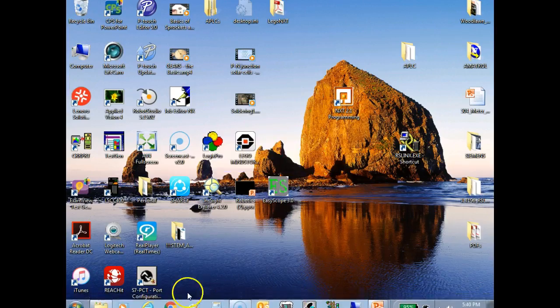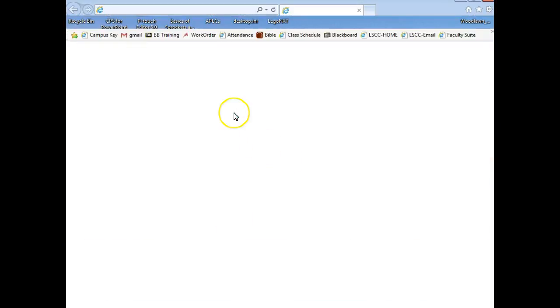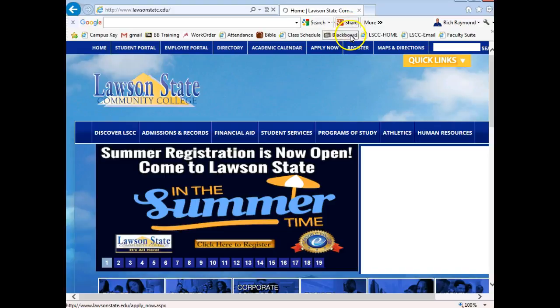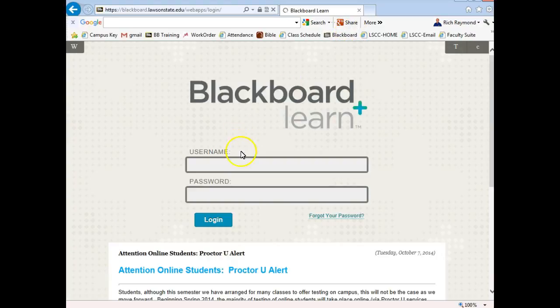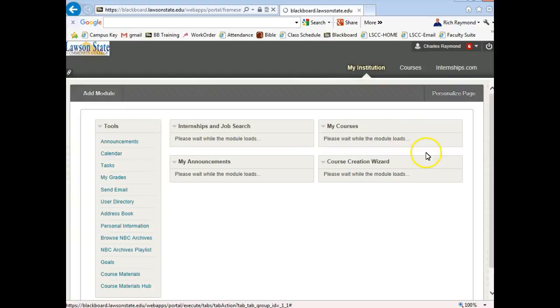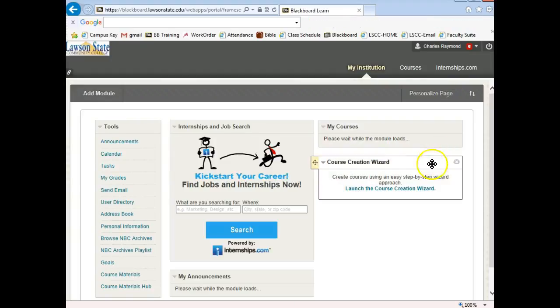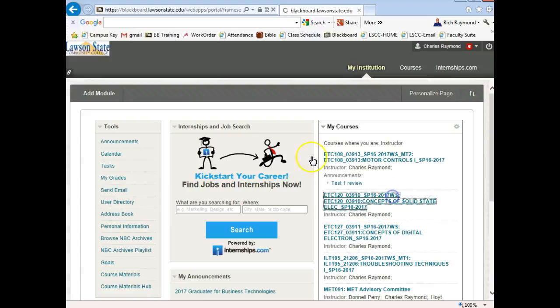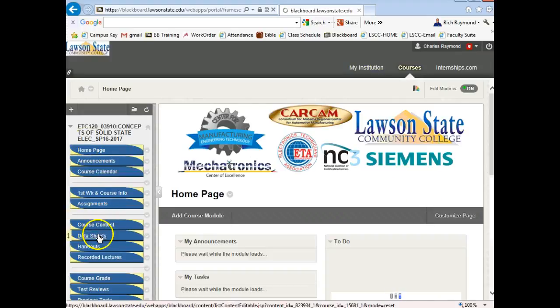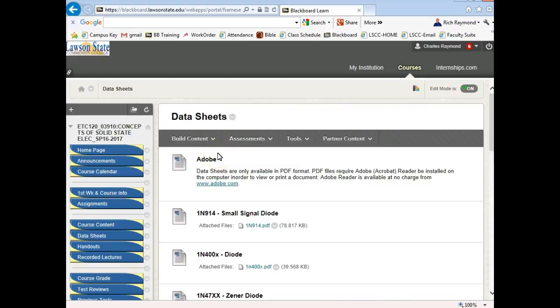So if I look at the data sheet, y'all bring up Blackboard and let's look at some data sheets. I think we have a 7400, and I think we got like a 74LS04. We'll look and see. So these were the ratings that we were looking at. But like I say, you need to understand fan out because you're going to read about it. But data sheets don't give fan out because they don't know what you're going to be driving, right?